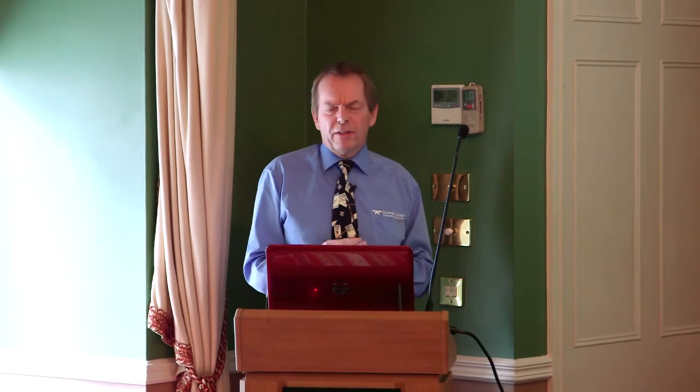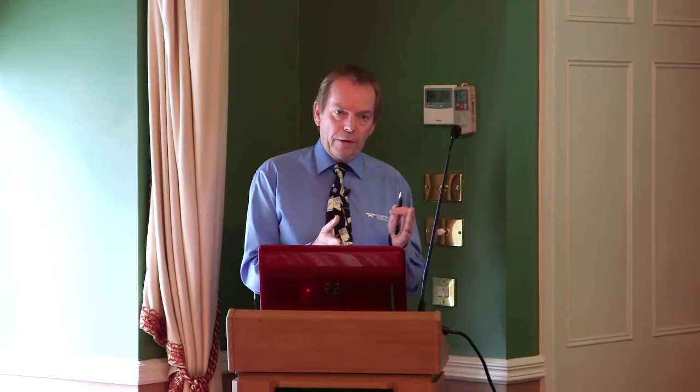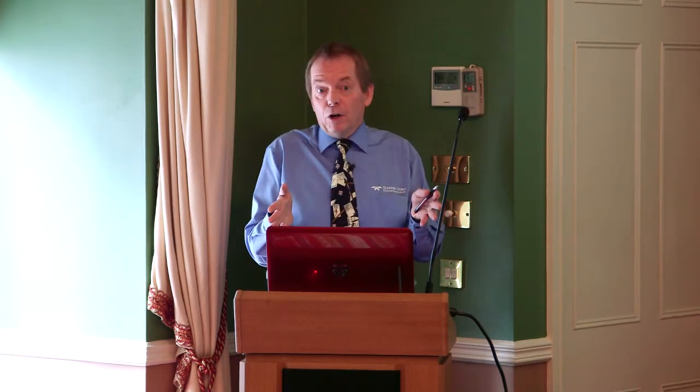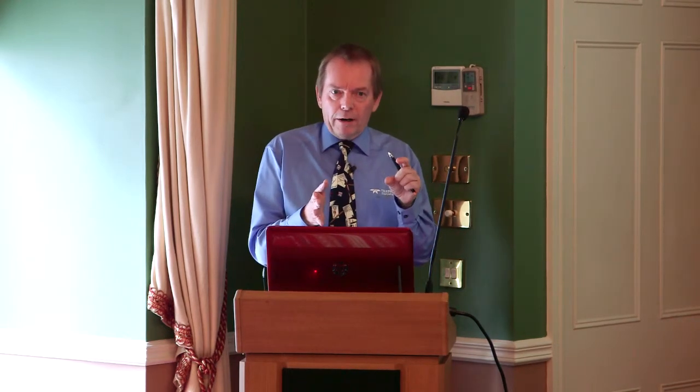So higher speed things like radar, for instance. If you're working up there and you want to look at chirps and chirp bursts up in the gigahertz range, you can't do that repetitively because the burst is a changing frequency, and it's difficult to get a good trigger. You can do it in 8-bit. That's the only way we can do it today. But the 12-bit would give you much finer granularity, particularly for things like reflections.